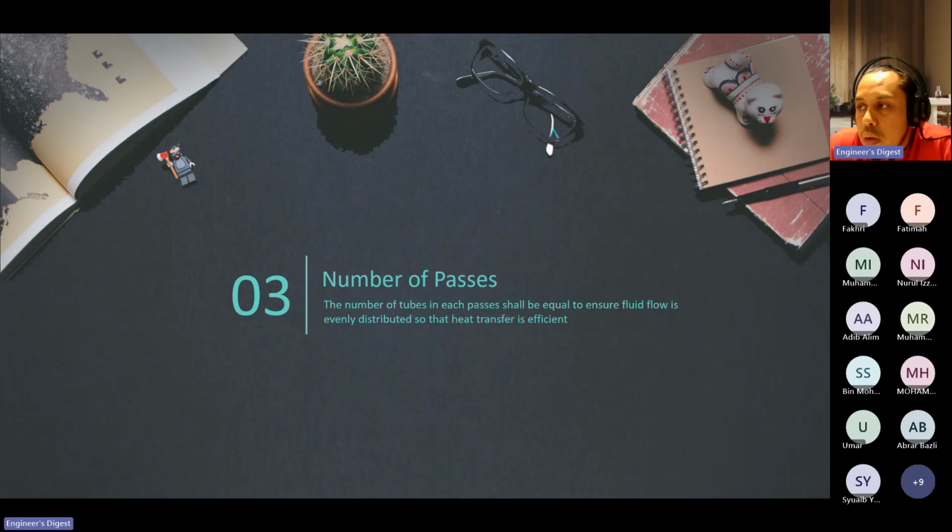Then depending on how many tubes we need to plug, we will check against the design margin of 10%, and we will also check with PED whether the number of plugs will affect the heat duty. If it affects the heat duty, then we require a permanent solution, which could be to order one more tube bundle.